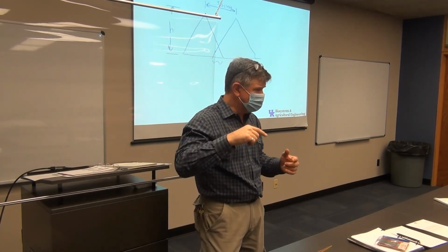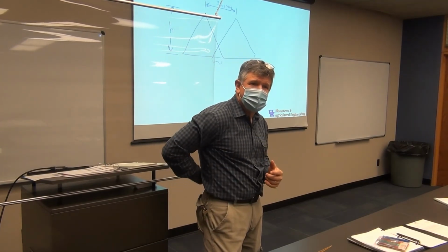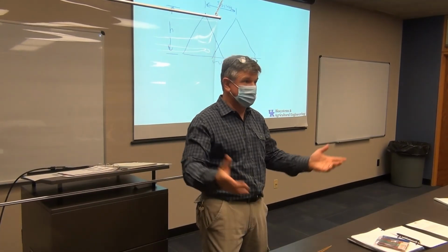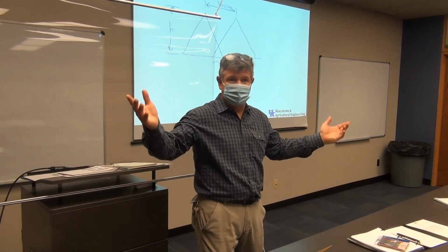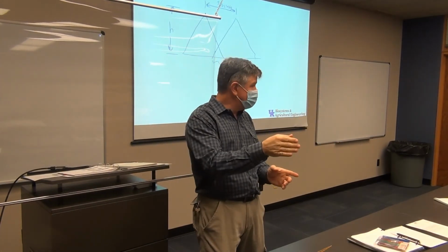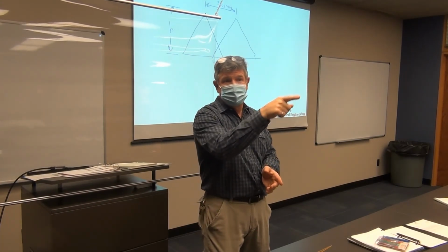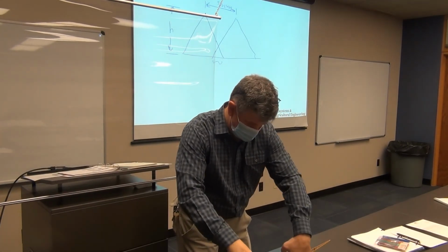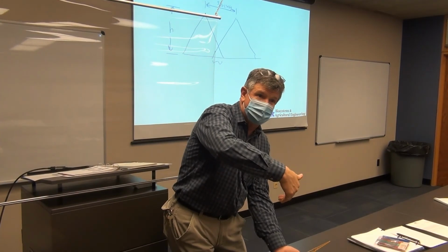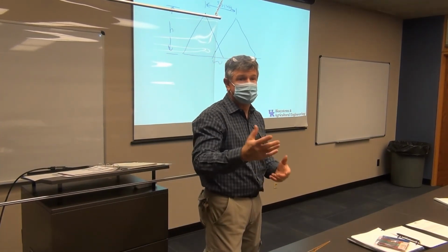I see a lot of wrinkled up foreheads going on. I'm not sure I buy that. What's the chart for it? So the chart would be, if I have 28-inch nozzle spacing, my sprayer is set up on 28 for whatever weird reason, I want to be able to go to a chart and say, okay, at 28 inches, here's how high I need to run my boom. So then I know to figure out where the boom needs to be to get 40 inches or whatever I need off the ground. So that's what the chart's going to tell me.